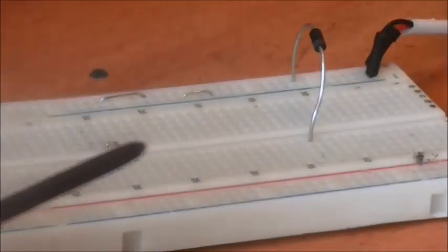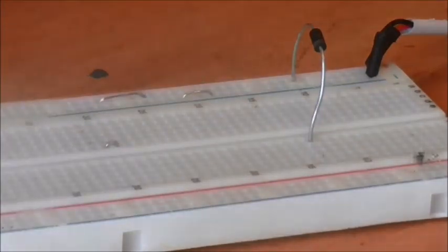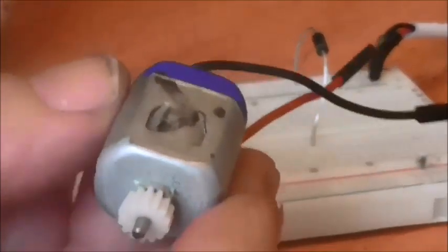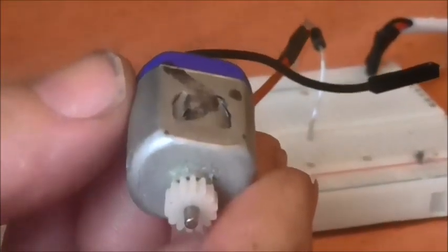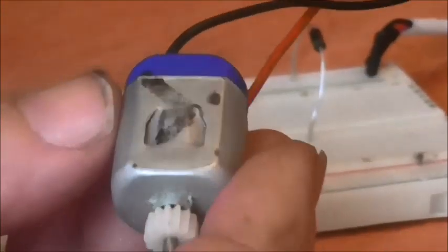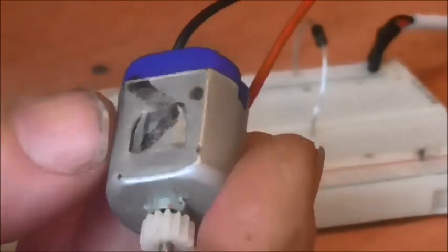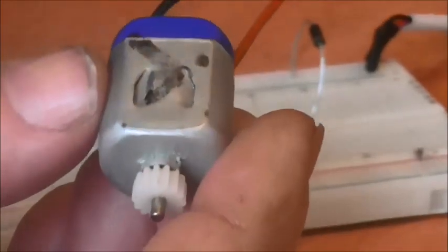The experiment we're going to do here is designed to illustrate that. So I have a power supply here, and I've got a positive rail and a negative rail. I also have a diode. We're going to ignore that for the time being, and what we're going to do is put in a motor. It's a bog standard little toy motor. It's a DC motor. It has coils on the rotor and two permanent magnets on the stator.